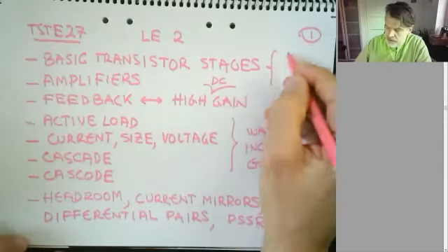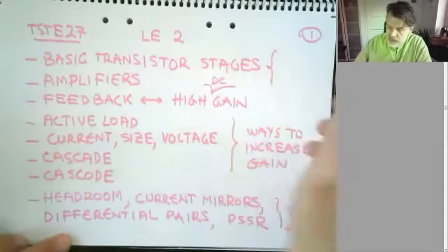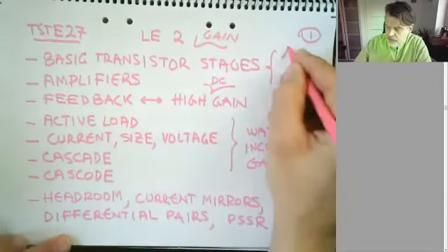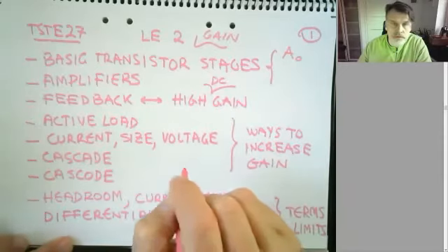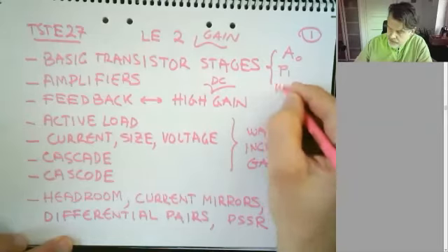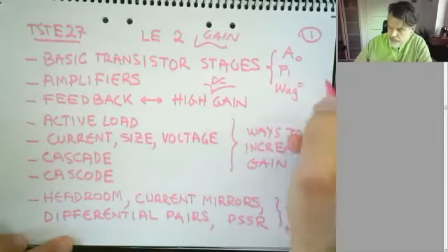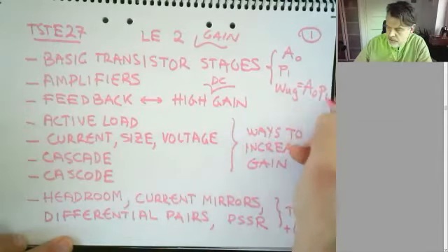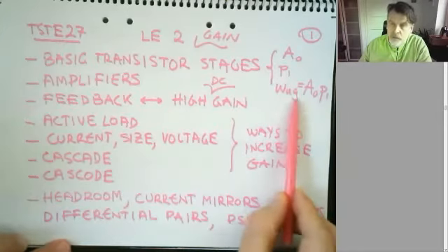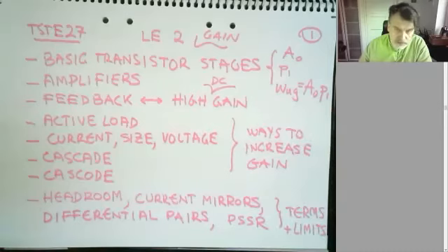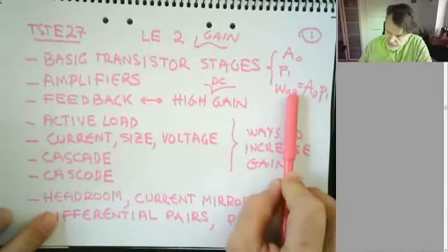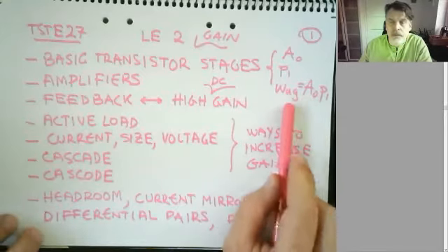We had a transistor gain stage. So we had typical parameters like the A0, the DC gain, the pole, and the unity gain frequency were important parameters, which is approximately A0 times P1. I argued last time that omega UG is a parameter which is typically hard to increase. It has a high penalty in terms of power consumption, and